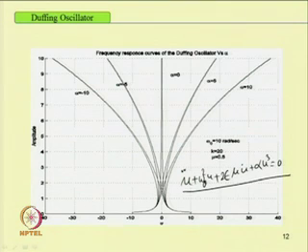If you take this equation, already we know the frequency amplitude relation in this case. Unlike the linear system, that means if you put this alpha u cube, the nonlinear term, equal to 0, already we know in case of the linear system, the steady state response of the free vibration will tend to 0. If this mu, that is the damping term, is very small, that is if we have an underdamped system, we will have an oscillatory motion, but finally the response will slow down to 0. But in case of this nonlinear system, we already obtained one frequency amplitude relation.